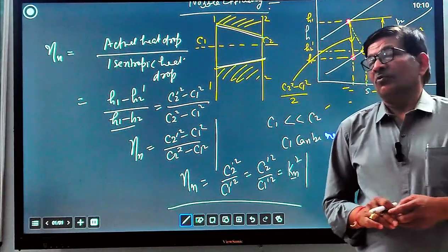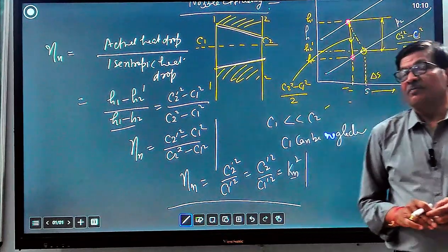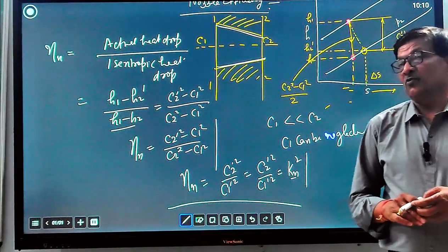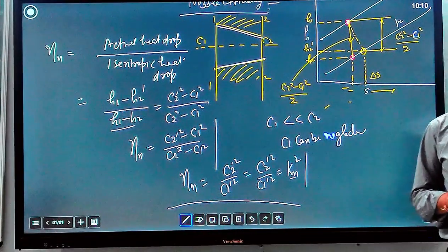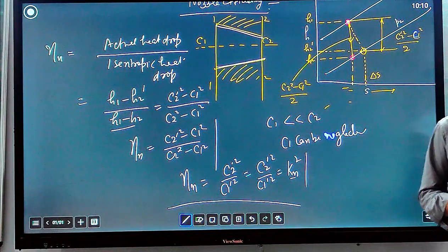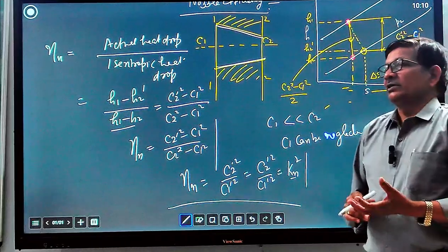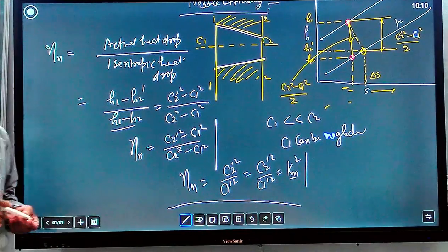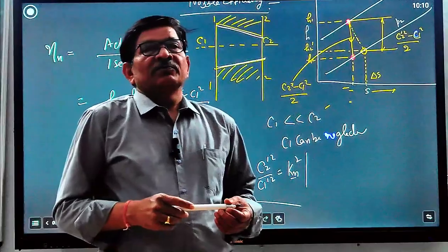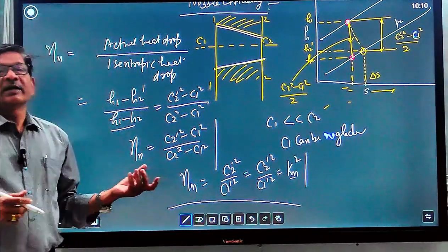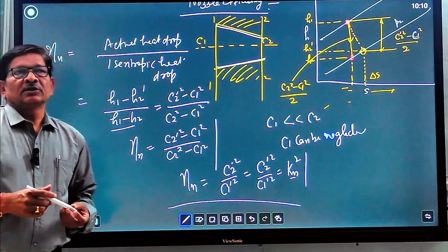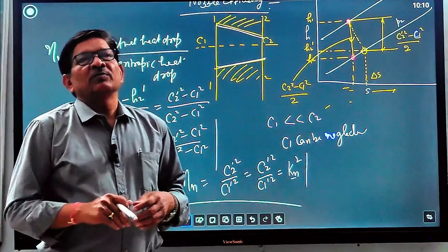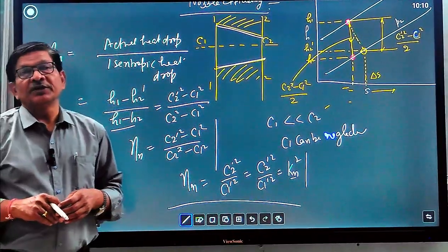So in that case, more frictional loss will be there. So we must keep a very careful design of the convergent divergent part of the nozzle so that flow separation will not occur. So how do we decide the diameter of the diverging part, meaning what will be the length of the nozzle in the divergent part? We have to decide because, according to practical constraints and applications, we have seen that the angle should be between 6 degrees to 12 degrees. The divergent angle should not be more than 6 degrees, but the maximum allowable angle is not more than 20 degrees